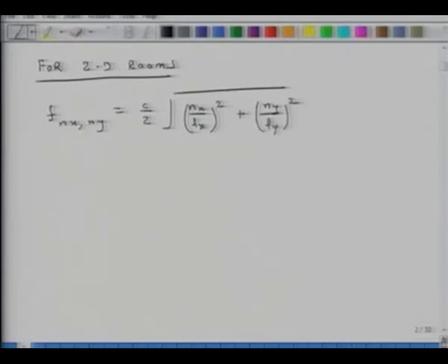And we had also shown that the angle of incidence of nx and yth mode or natural frequency of the room has to be tan inverse of ny times lx over nx times ly. And based on this understanding, we had shown some natural modes of rooms.